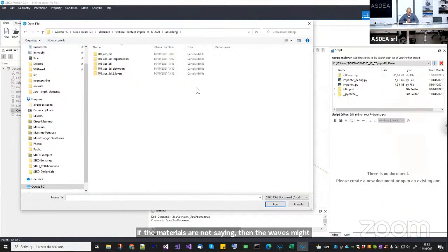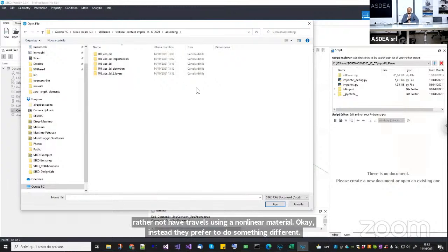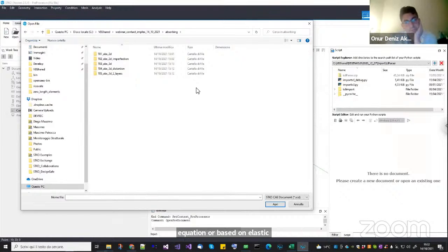Yes, right, this is true. The point is that I had the option to use either a material or a linear elastic behavior there. The problem is that the whole theory about the absorbing boundary is based on the elastic wave equation. So I think I could have had a lot of trouble using a nonlinear material. Instead I prefer to use a linear material inside, because those equations are based on elastic wave propagation. But then I let the user update G.